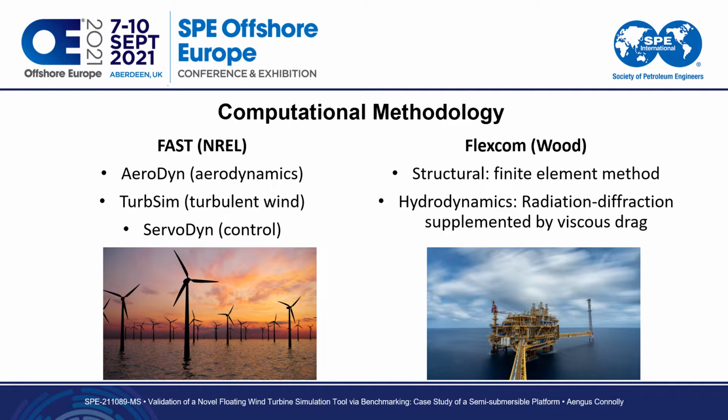element solver. It also has hydrodynamic modeling capability, so it accepts data from radiation diffraction solvers from potential flow theory, applies these as excitation forces to the floating structure, supplemented by viscous drag forces, which are modeled using Morison's equation. So the two tools combined provide a fully coupled aero, structural, hydro modeling tool.